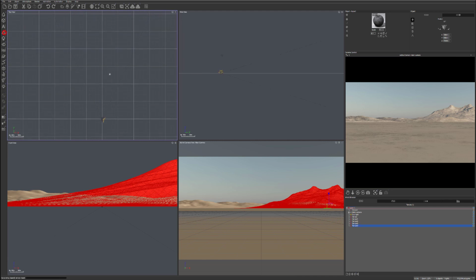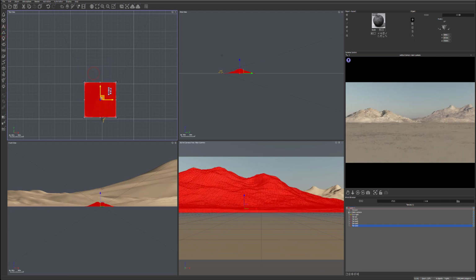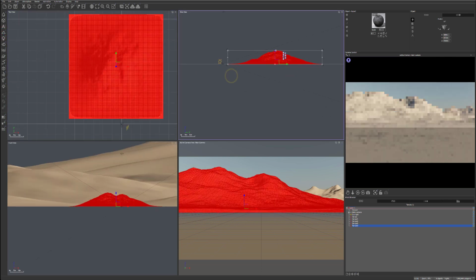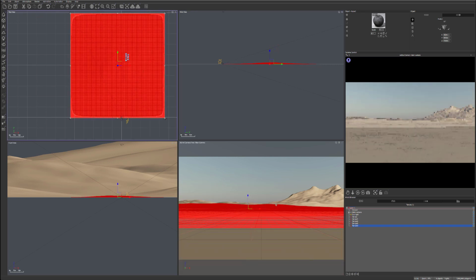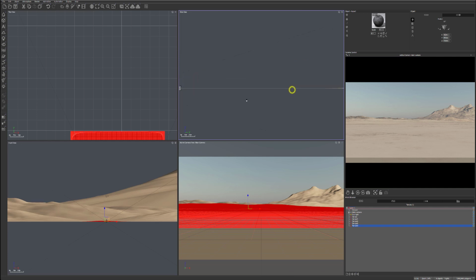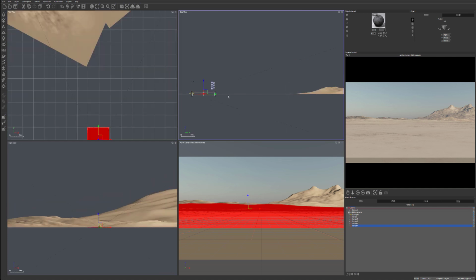Let's create a new height field terrain, and this one will go up front, and let's make it a little bit flatter. The interesting thing when we do it this way, you can see we come right here and it's covered because we have this hill, all this area between this mountain and our terrain will be hidden by the terrain we created. So we don't need to create any additional polygons or other things. If you do animations, if somehow your camera will start moving there, you need to think ahead of this and maybe create additional terrain there.